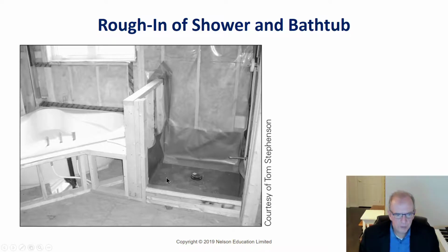Very important if you're managing this process that this is protected so that somebody doesn't, because I don't know what it is, but there's this burning desire that people have to drop drywall screws on this pan and then stand on them, and that cuts the pan, and that means it's going to leak. They're going to put a concrete base in here, but the moisture is still going to go through the leak, and that's when you're going to see stains on the ceiling down below. It's not going to flood, but it's going to leak enough that it's going to cause a problem.